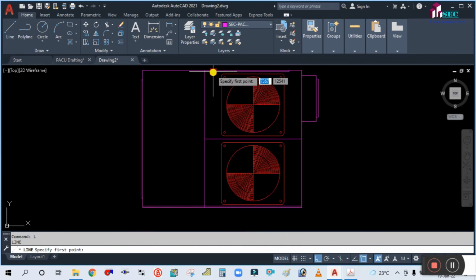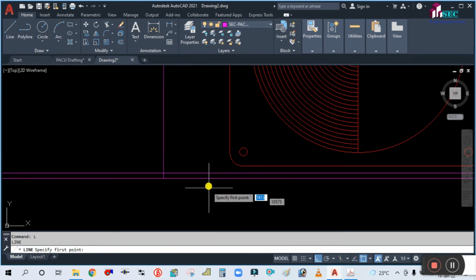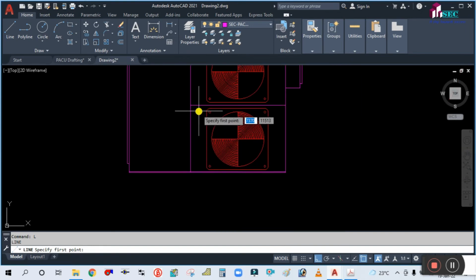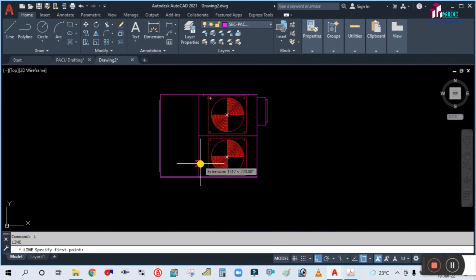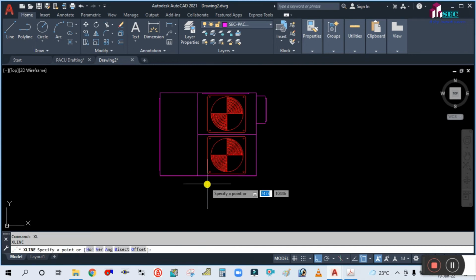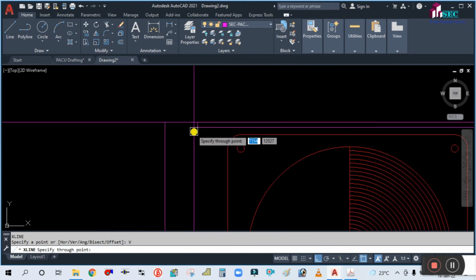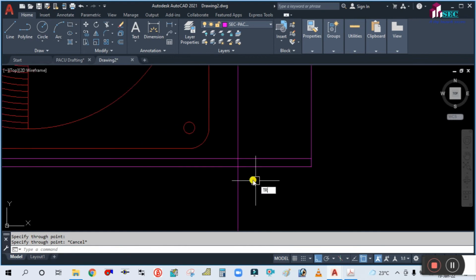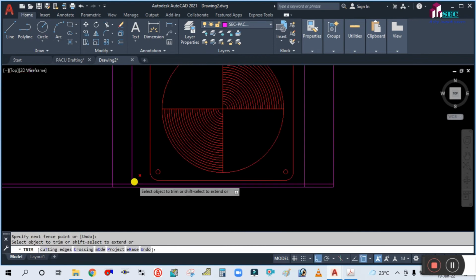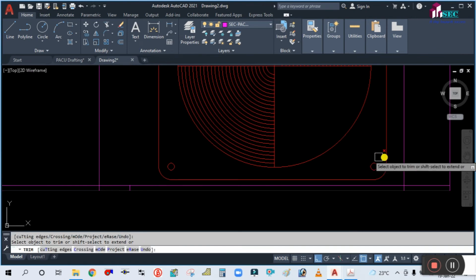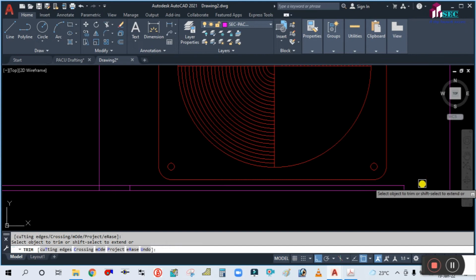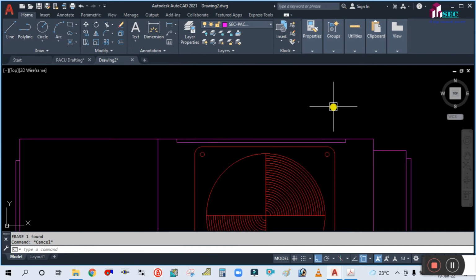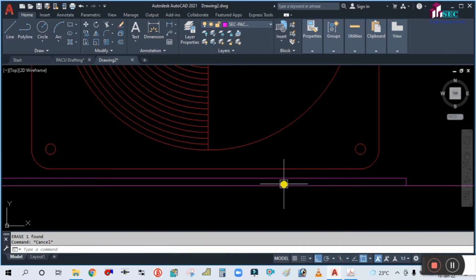Similarly, you have to drag this line, drag down, or you can simply use Extend, type V and click here and here. Now TR double enter, also trim this, select and erase. Okay, so you can see this also, and now you have to change the line type.